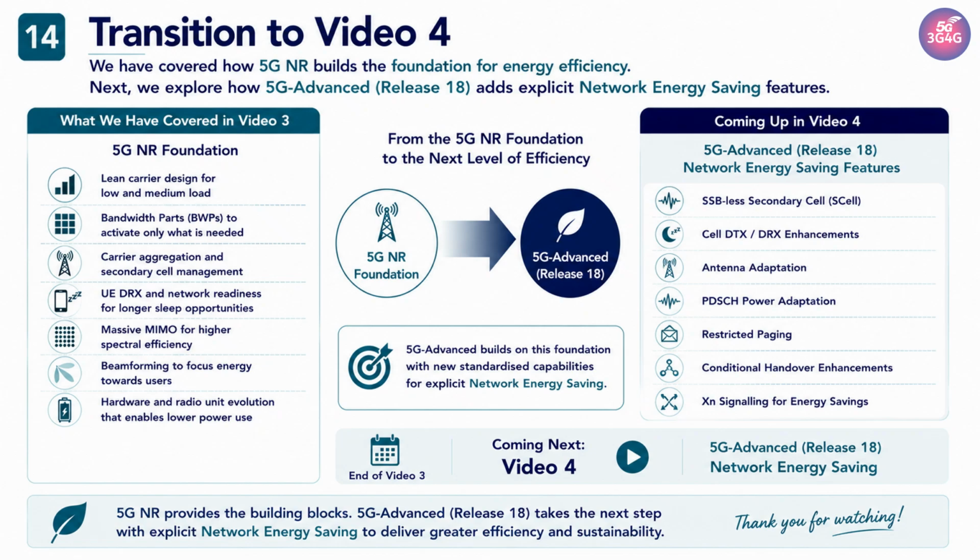We then looked at lean carrier design, sleep opportunities, low and medium load operation, bandwidth parts, carrier aggregation, secondary cell management, UE DRX, massive MIMO, beamforming, and hardware evolution. The main message is that 5G NR provides the building blocks for more energy efficient mobile networks.